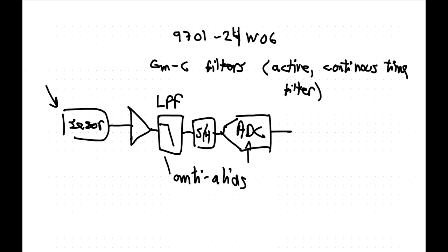Does anyone know? Is the anti-aliasing built into your off-the-shelf ADC? Oh, this is really embarrassing. We should all know this. I know, because we always just rely on there not being high frequencies to alias into it. Yeah. Most microcontrollers do not have a low pass filter built in. Right, okay, well, you've got to do it then.